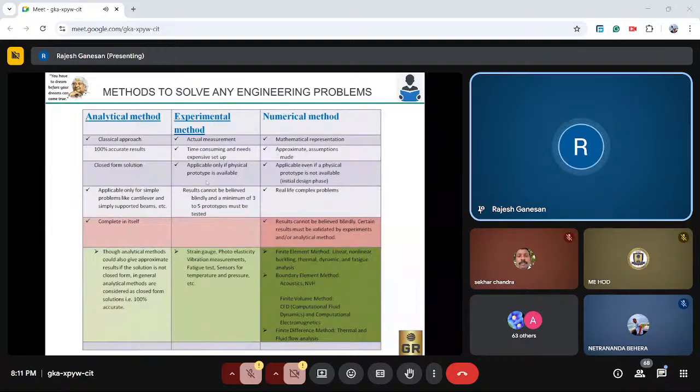For example, in bulk products, if you are making a bolt or nut, first I will create a single bolt or n number of bolts, like n equal to 10. I will inspect whether everything matches the application, and only then go for bulk production. In a similar way, I am validating everything for the physical prototype. With respect to physically available equipment, such as strain gauge, elasticity methods, vibration methodologies and fatigue tests, we already have different kinds of equipment in the inspection area.